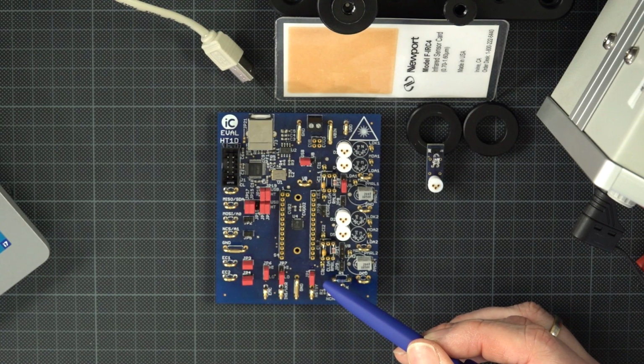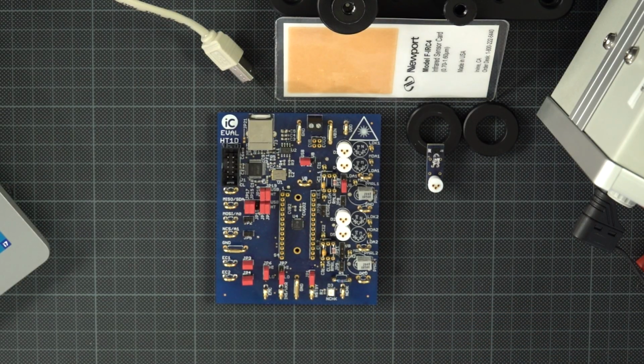Important to know are 3 of the chip configuration jumpers which might prevent light output. JP1 should be closed so that the chip is active and not in standby. The output channels have to be activated by closing JP3 and JP4 respectively on a pin configuration level. In addition to the pin activation, the 2 channels will also have to be activated using the software GUI.